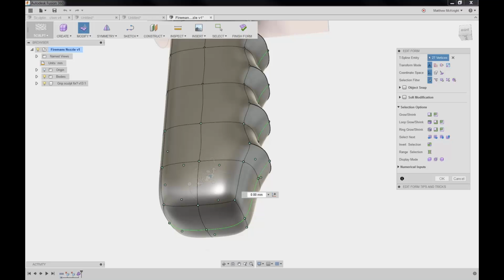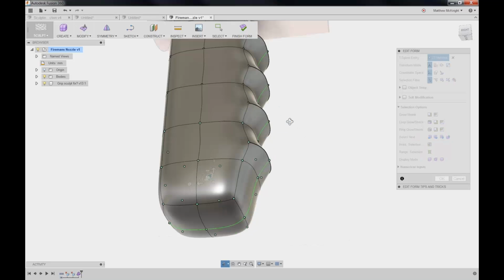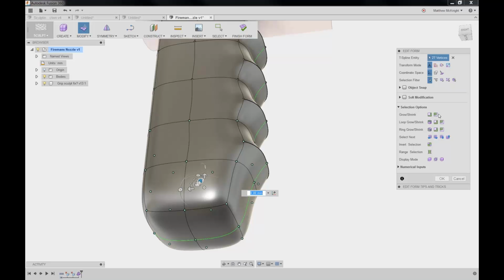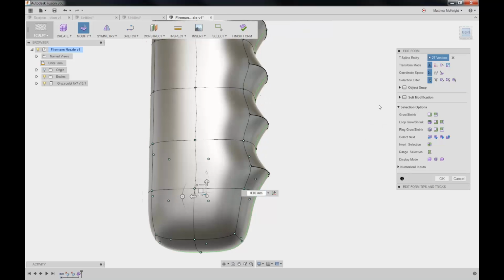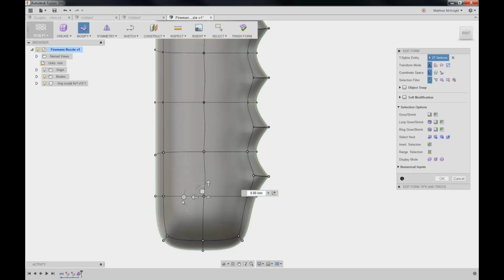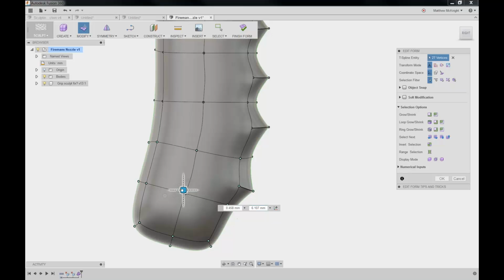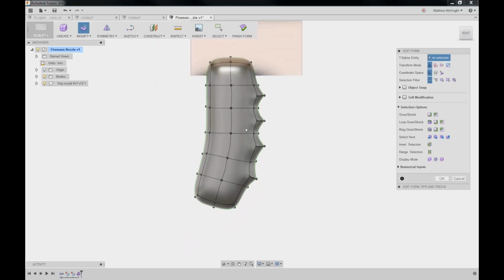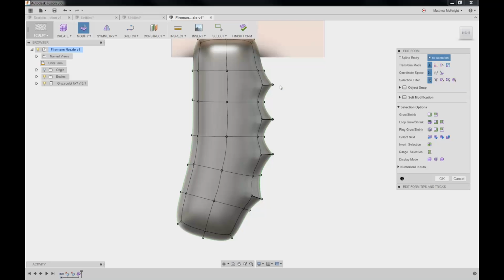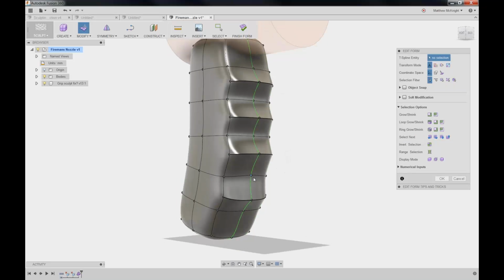And you can see it's gone through and it's grabbed a whole bunch of additional vertices, growing those up. We could shrink those down if we didn't want them, the additional ones in place. But we can now use these, and we'll use those to manipulate our geometry. So we'll rotate them. Gives us a nice transition down at the bottom, and we'll position them over a little bit further. So we've got a little bit of a change, an arc to the end of our handle. Now the one thing that you'll note is that one of our vertices didn't move, and that's because when we used our grow command it actually didn't grab that vertice.